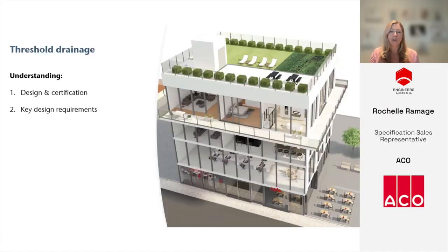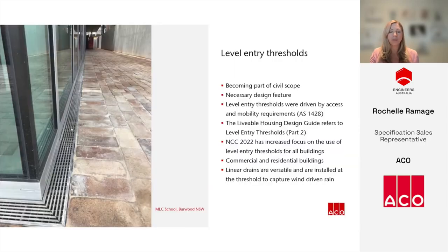Threshold drainage starts with two things, design and certification, and understanding the pavements and door system around the entrance. The door type, the slab depth, the membrane detail, all of these influence the drainage solution. Once you understand those constraints, the rest of the detailing becomes much clearer.